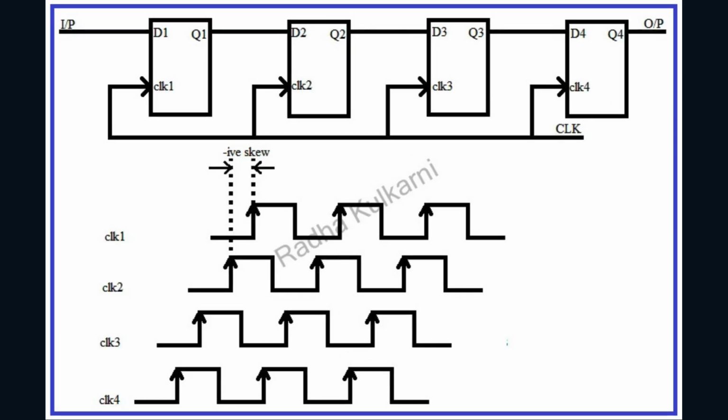Right, negative skew is when the clock arrives earlier at the destination flip-flop B than at the source A. The clock edge at B is pulled forward in time. This earlier clock edge means the data has less time to travel from A to B and be ready before the setup window closes at B. So negative skew makes setup time violations much more likely. Less time for the data to arrive. That sounds bad for setup. It is generally bad for setup time.